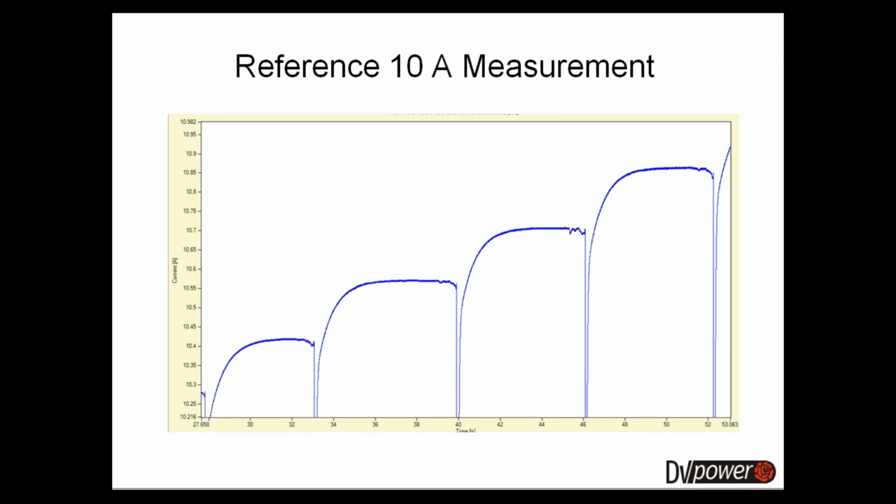This is also an important step because you need to have a reference in order to have something to compare to when you actually detect a problem. So even if your transformer does not have any sort of problems, the graph that you recorded on it is still valuable, because later when you do have problems, they will be more easily spotted by comparing it to the graph you recorded back when it was in good operational condition.